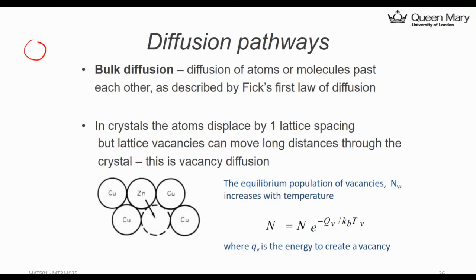Okay. So bulk diffusion is when you have a lot of grains. The atoms move around within the grain. Basically, that is bulk diffusion, and it follows a force law. In this case, if you look at the graph here, that's the vacancy for the atom to move. Equally, there is a similar equation governed by this probability equation: activation energy, temperature, and the Boltzmann constant, which is related to the universal gas constant.